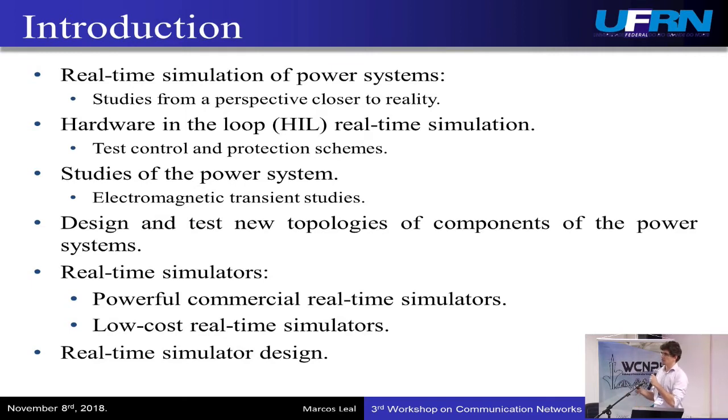One of the main reasons is the possibility to perform hardware-in-the-loop real-time simulation, where we can have a control or protection scheme in a closed loop with a system being executed in real time. Also, you can have a commercial relay in a closed loop with a real-time simulator.